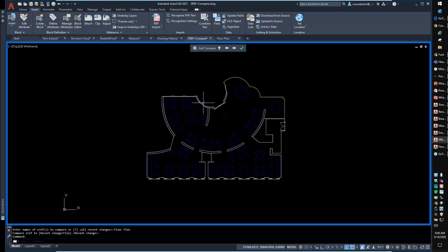less than 1/1000th of a millimeter, it will not pick it up depending on the size of the drawing. If the drawing is very fine and it's 1/1000th of a millimeter, then yes, it will pick it up. If the drawing is 300 meters long, it will not pick that up. Is it comparing based on object handles or doing some sort of visual check? No, it's neither. The comparison is comparing geometry to geometry, X, Y, and Z coordinates of geometry. And actually, in most cases, it's just X and Y.